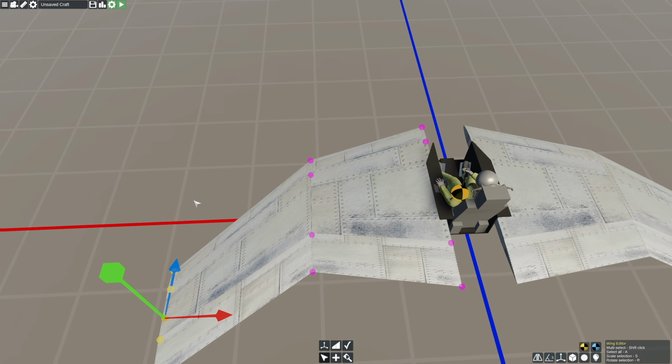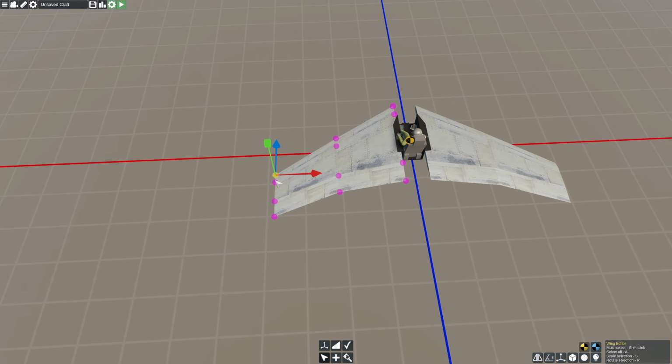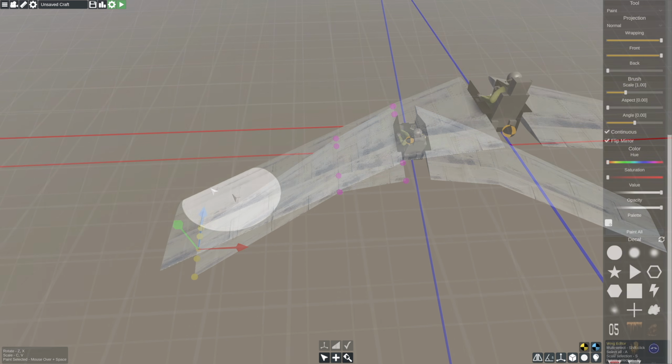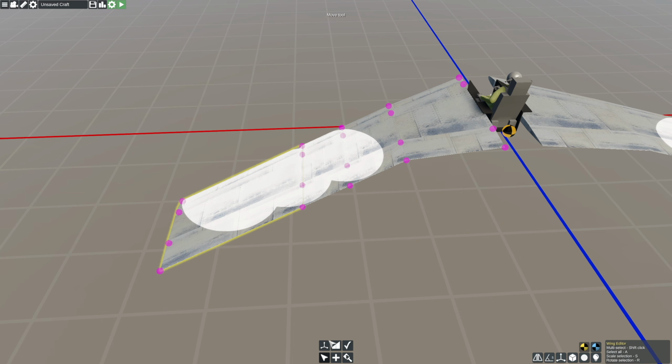When splitting a wing section, be aware that any settings the control surfaces had will be deleted, as the game is deleting the original parts and replacing them with 2 new sets of parts that match the shape of the original wing section. With this in mind, make sure you have finished splitting your wings before you start configuring control surfaces or painting the wing.